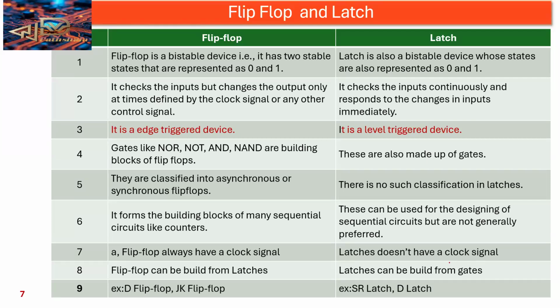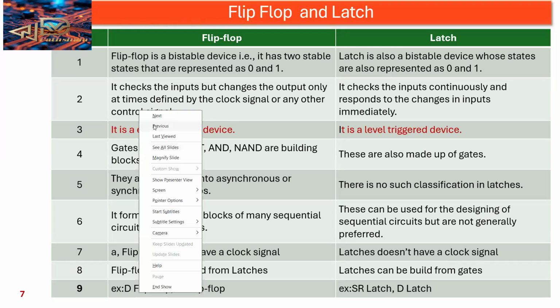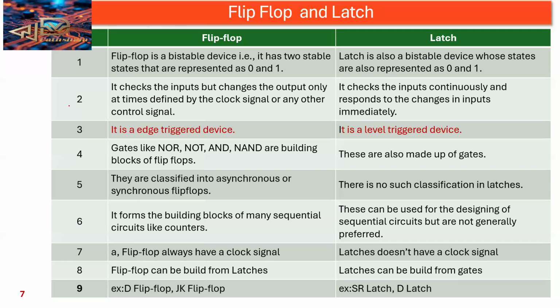What is the difference between the flip-flop and latch? Flip-flop and latch are both bistable, and both are 1 bit storage devices, storing either 0 or 1. The main difference is that the flip-flop works with the clock signal, and every time it depends upon the clock. In a latch, the triggering depends upon the enable signal, which acts like a clock here.